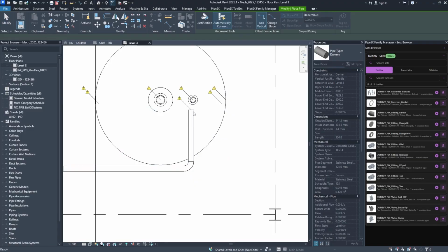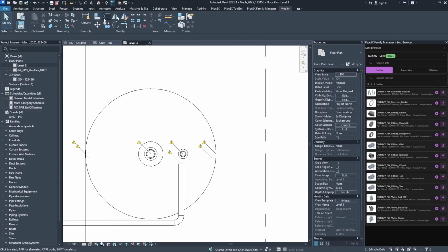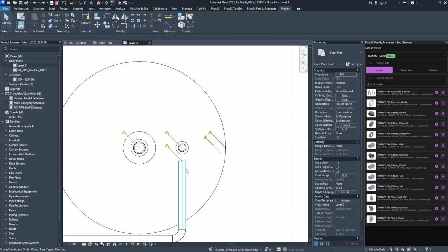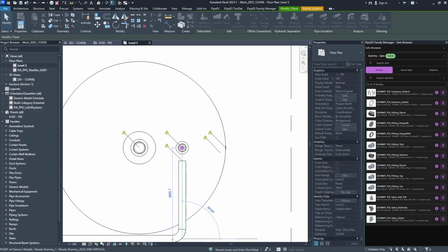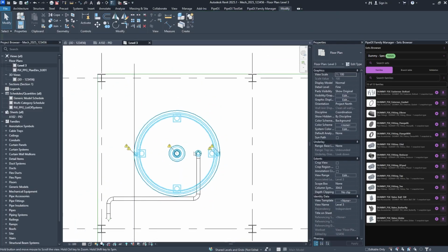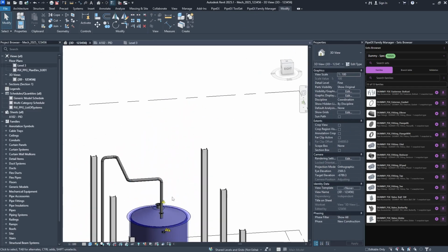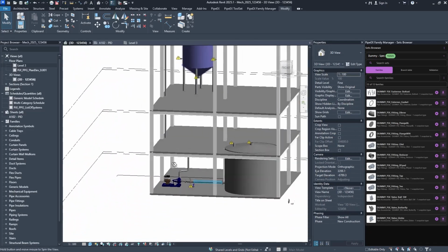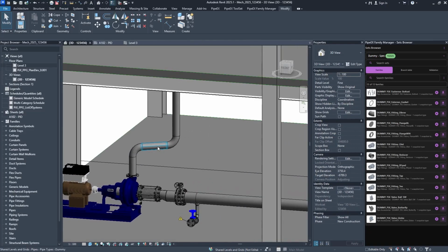You can do it by creating another section of the pipe and using the align tool. And then you can just connect it like that. As you saw, once I brought it right above the nozzle, there is an O-snap enabled towards the connector inside of the nozzle. And this is how the connection can be created. When we are done with the routing itself, we are going to create components on this pipe.